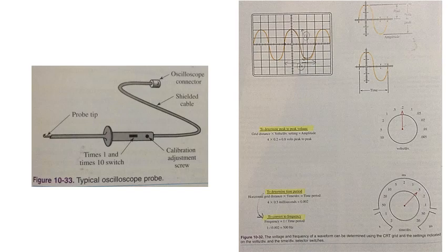The time period for the wave can be determined in a similar fashion to that used for finding the voltage. The time period of the sweep is set using the time div selector switch. The time period selector switch is marked in whole seconds, milliseconds, and microseconds. If the time div selector switch is set at 0.1 milliseconds, then each grid space is equal to 0.1 millisecond.